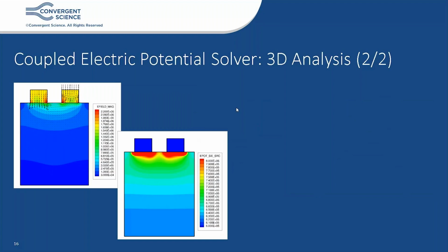This can allow engineers to better analyze the electrothermal behavior for that particular battery. In this pouch cell design, both tabs were on the same face. So you have high current density on the top face, so you get more heat release on the top face. So you're going to get higher temperatures on the top face than the bottom face. You're also going to get sharper state of charge drop on the top half of the battery than the bottom half. So the battery is inefficiently operated or consumed.